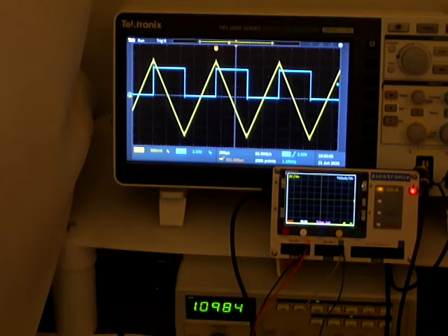a set of options and instructions. The one on the left, set, takes you to a higher level of menu where you can set things like trigger polarity, trigger source, types of display, various things like that. This one, the second button, is the run button, which effectively either starts the DSO, stops it, or in single shot mode it fires off a single trace. The next one is a set of variables which you can cycle through by pressing the button, and that lets you set up various parameters. And the two right hand buttons, the yellow and the green, allow you to go up and down through menus.